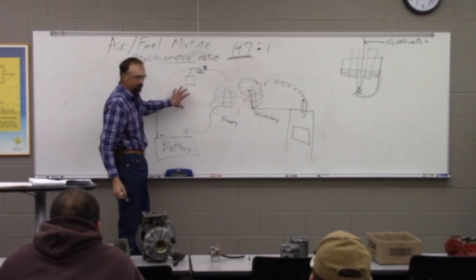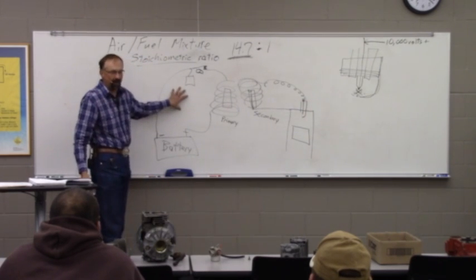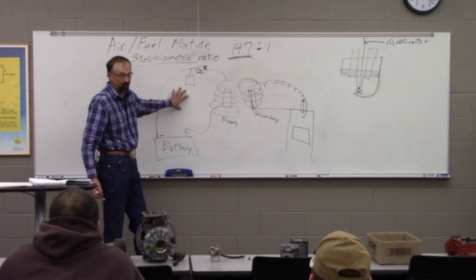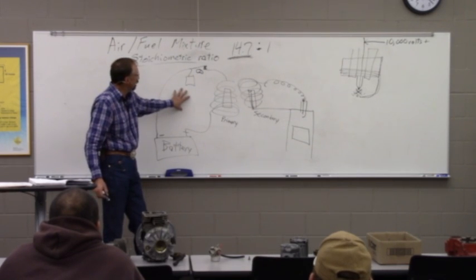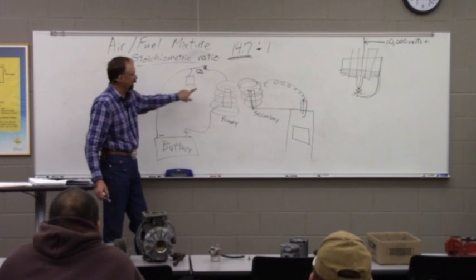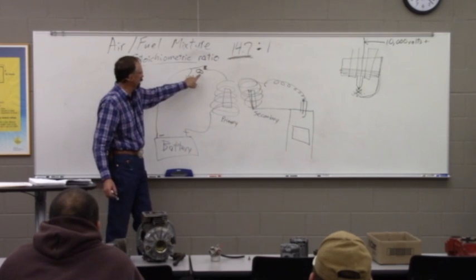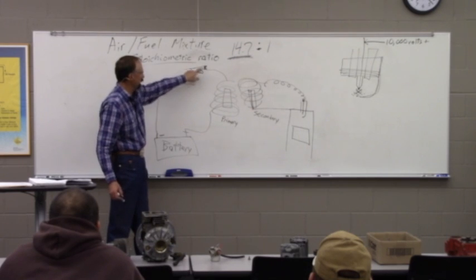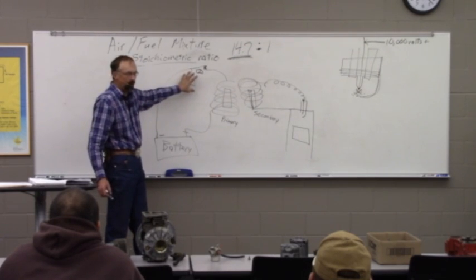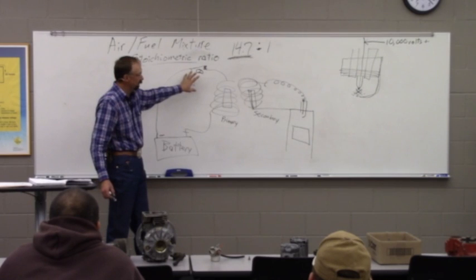But in this type of a system, which we haven't seen in anything manufactured in automobiles since 1975, I think, and of course this was in combination with carburetors, you were looking to replace these points and replace this condenser and adjust how they were operated every 10,000 miles.